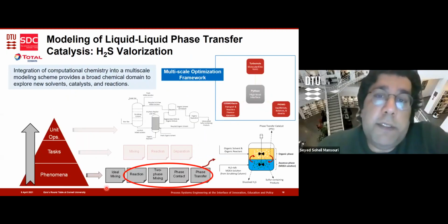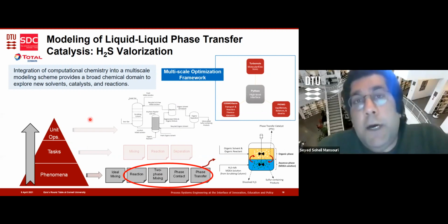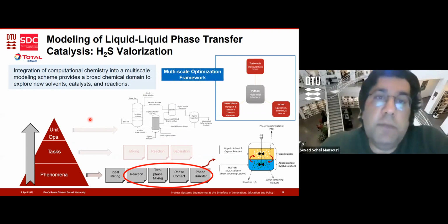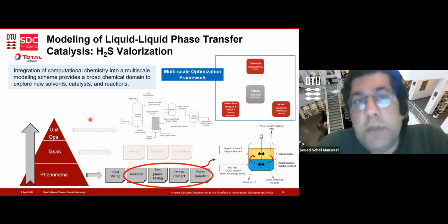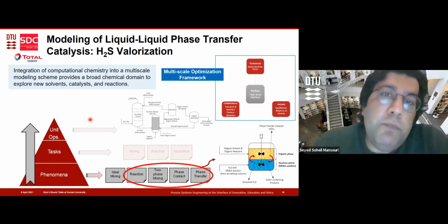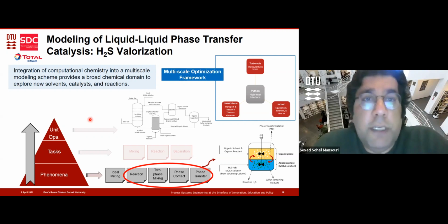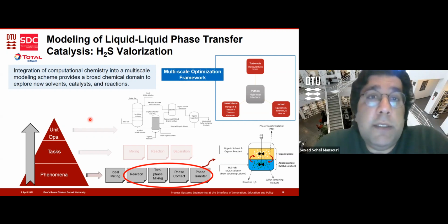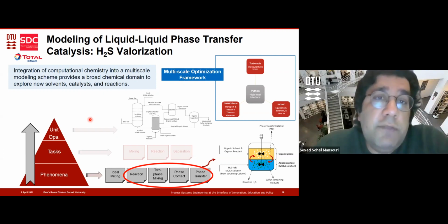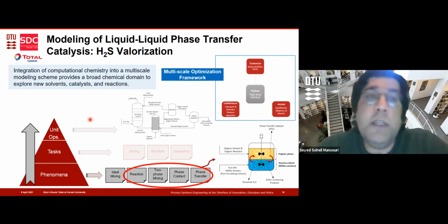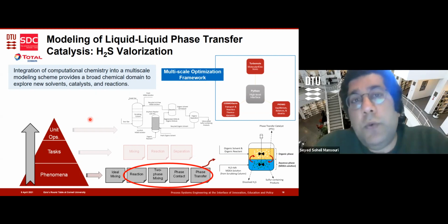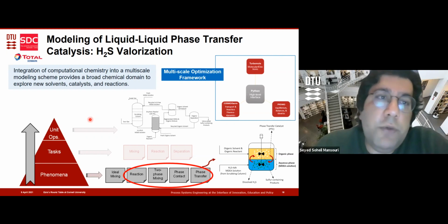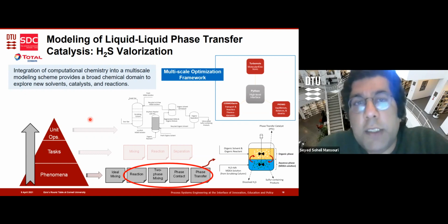Another example is where we look into process intensification when it comes to sustainability. A lot of times when we are talking about hazards, traditionally the objective is to look at the hazardous compounds that are produced during processes as something that we have to spend money to mitigate. One of them is hydrogen sulfide. It is a gas, or molecule, that is quite abundant and harmful in oil and gas production, and it also incurs a lot of costs on this industry, along with environmental challenges from the chemicals that are being used to mitigate it. So here we have started looking at it from another angle, asking: what if this is still a raw material? Can we find a solution where we generate revenue and convert it to a more sustainable product that can also have an application?